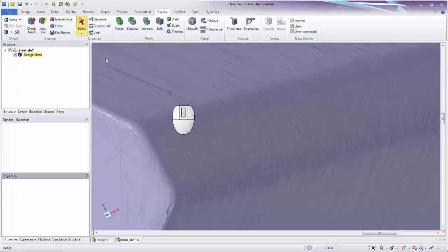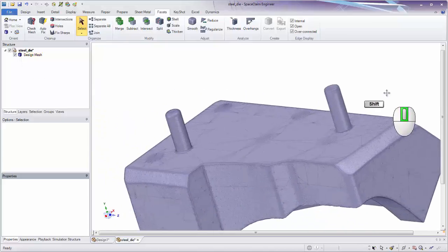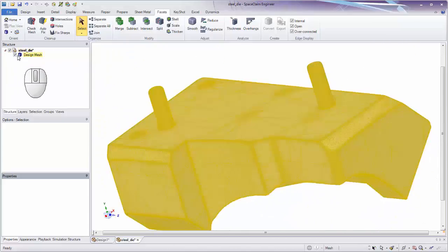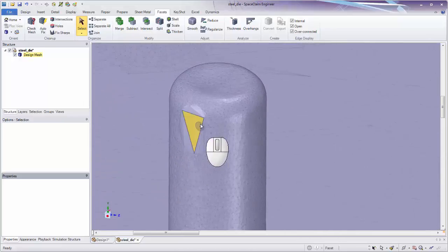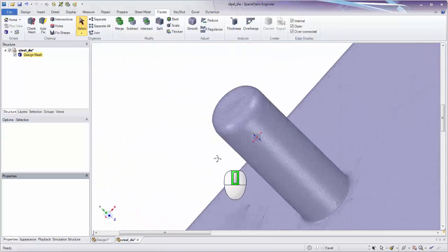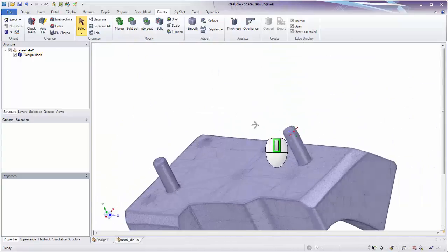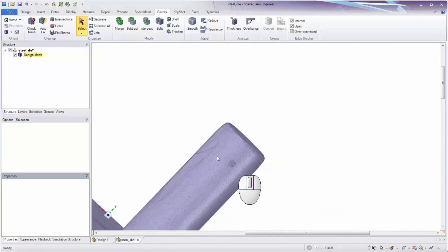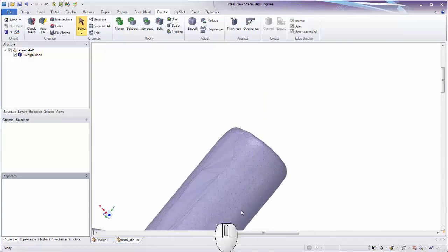So you can see that using the check mesh and autofix and then deleting some bad facets is a super quick way to turn a non-watertight corrupt STL into a nice, clean, watertight, solid STL. Again, the only limitation is the way that it caps in those faces right there. So we can see that this one is flat across instead of following the contours. And same thing on this one. It did a flat straight across capping instead of trying to patch it in following the contours.